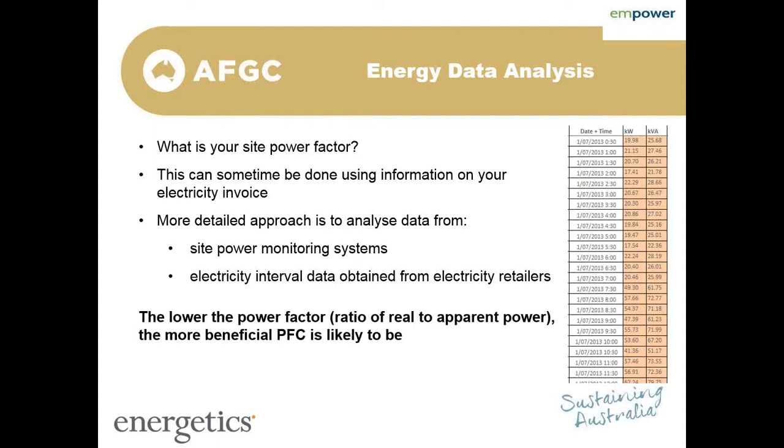But if you want to do a more detailed analysis, particularly if you have a monthly demand charge, or you're curious and want to get a better handle on it, you can request interval data from your retailer. You can see there in that example the kilowatts and the kVA for each half-hour interval throughout the year, which is useful information in itself.